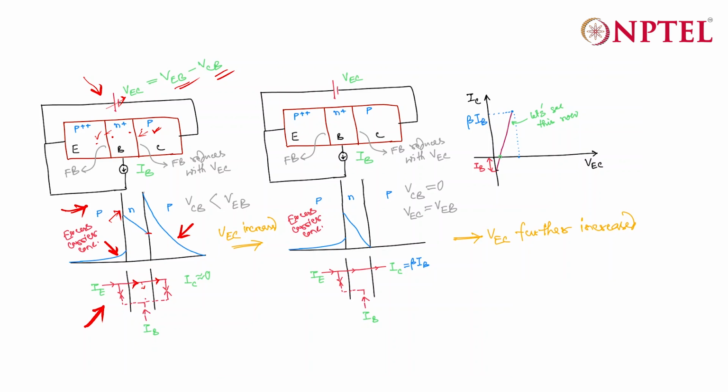And for electrons also, the electrons will now go from base to collector junction as well as from base to emitter junction, the way we described previously. And the recombination in the base region will be very, very negligible in modern transistors, and we can neglect this. And you will find that most of the hole will go from emitter to collector. And this is very much understandable.